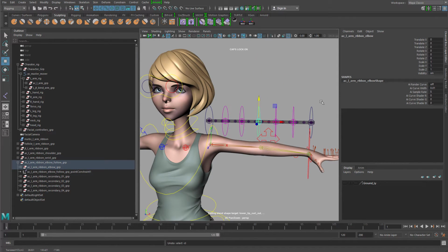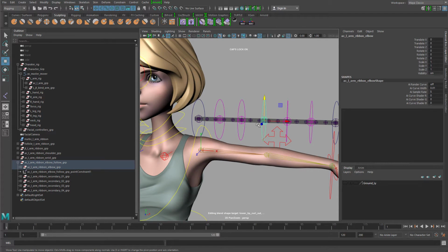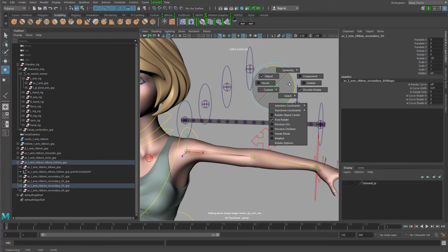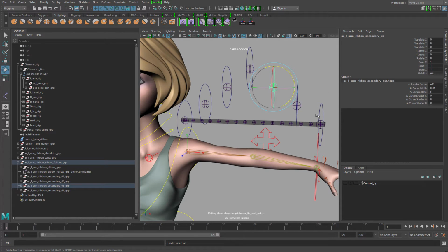After that, you should be seeing the nice linear transition, so they'll always be kept in straight lines. Now one last thing is that when I drag this middle controller up, I want that controller to be actually oriented, or changing its direction. To do so, all you have to do is an aim constraint on it.